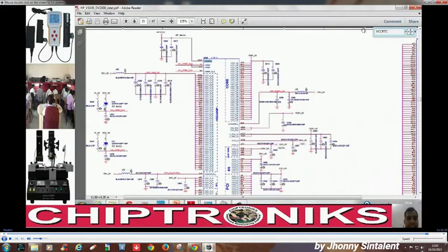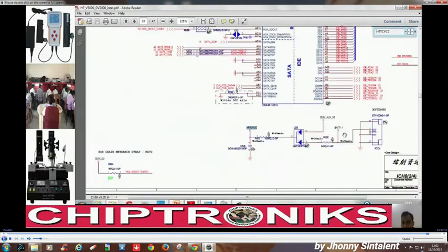So we have to check VCC RTC. Now I know VCC RTC is fed through plus RTC VCC. Now we have to check where this RTC VCC is coming from. Plus RTC VCC is coming from this supply or this battery supply. If this is missing, then what can happen? Either these two are missing or these two components are faulty. So we have to now check this signal.